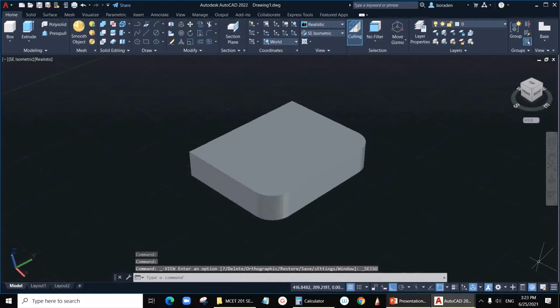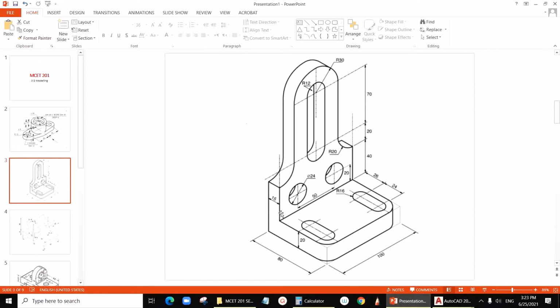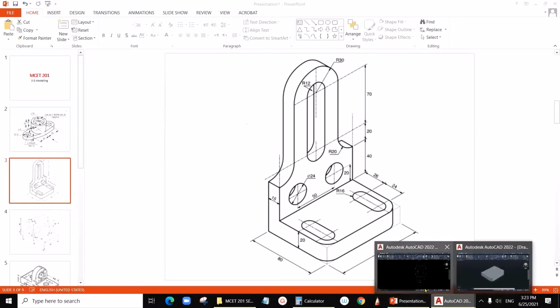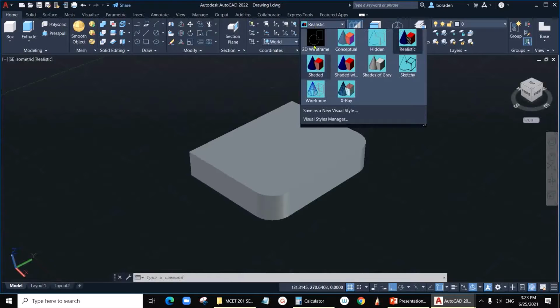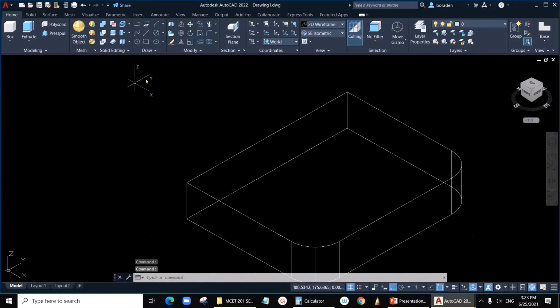Now this 80 by 100, after that I want to draw this rectangle up to here, which is 40 plus 20, 60, and this is 15 on the base of 80. So a 15 by 100 rectangle here on this base. So going to here, I want to draw. You can draw it by the rectangle command or by the polyline command, doesn't matter, or just by line command also, and then join it.